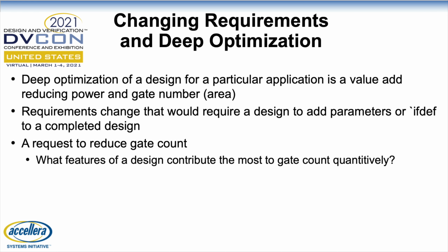And this general request to reduce gate count, I've actually seen it on customer designs where the design lead realizes at the very end that in order to fit on the die, to ease up the burden for timing closure and all the physical design, all the back-end constraints, they just need to reduce gates a little bit.